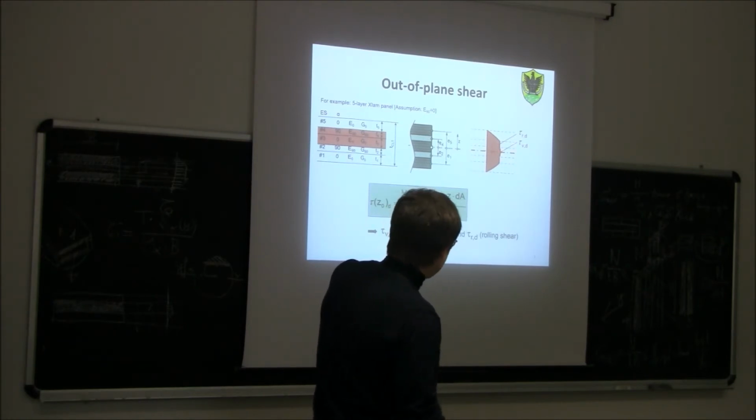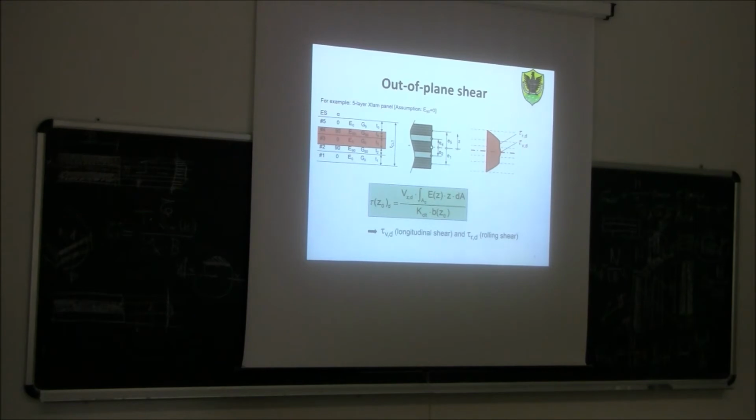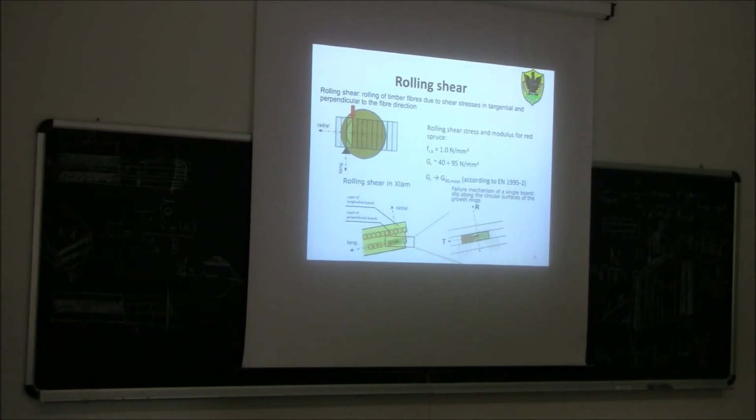But of course, I agree with you, this is the maximum shear demand. However, what we are going to see now is that the shear strength capacity will be completely different in this layer and the other two layers. Why is that? Because of the orientation of the fiber.